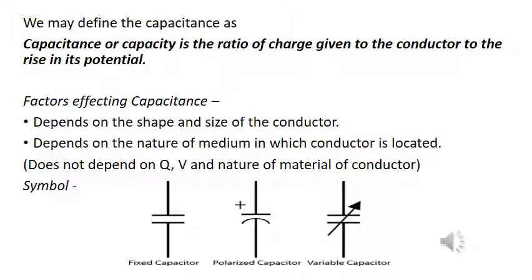The majority of electrolytic types of capacitors are polarized. Therefore, these are known as polarized capacitors, and the terminals of the capacitor must be connected according to its polarity. That is, it should be connected by its correct polarity, positive to the positive terminal and negative to the negative terminal, because incorrect connection will break down the insulating oxide layer and permanent damage occurs.